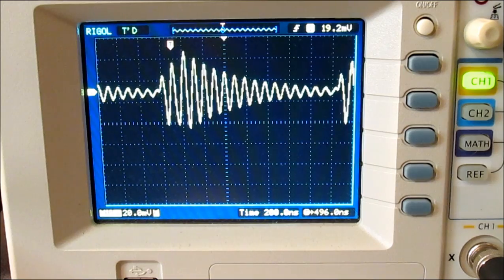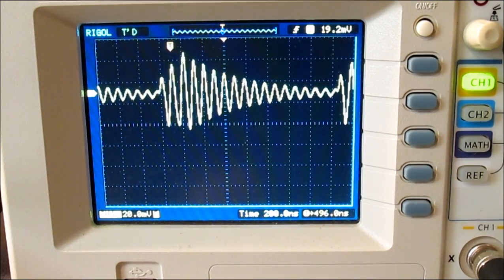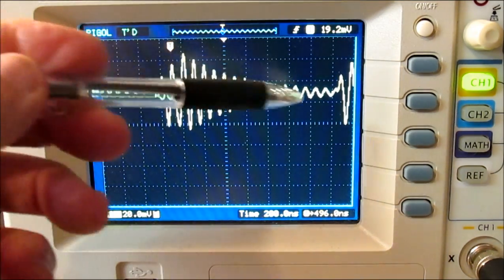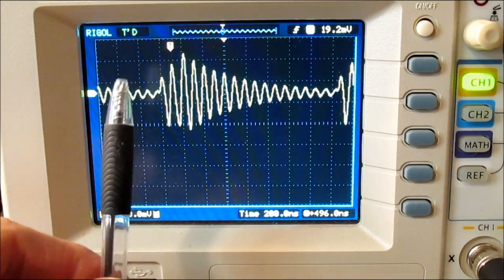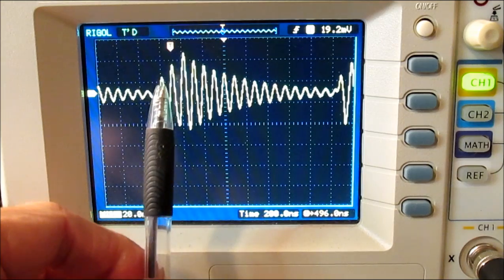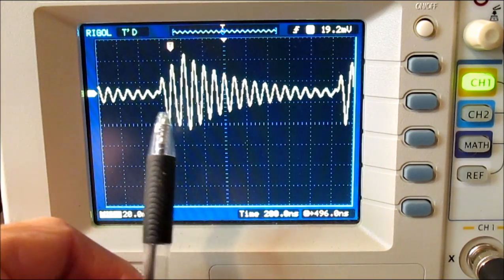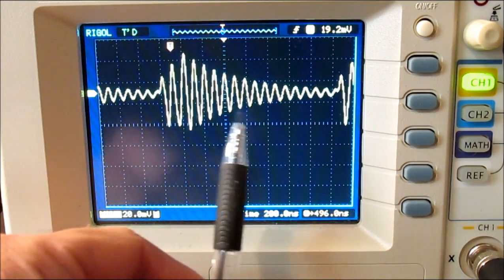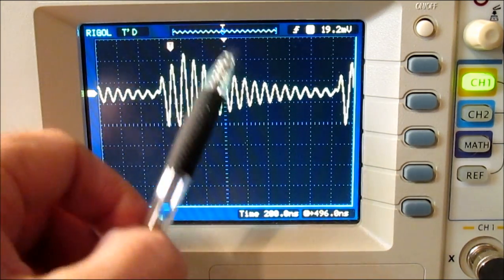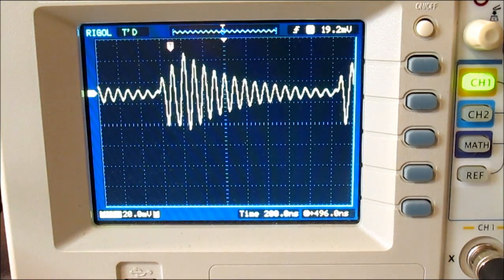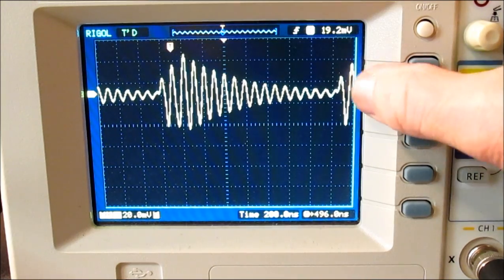Alright, now here's the oscilloscope with the ringing waveform on it. You can see when you're looking at the left edge of the screen, the amplitude is greater, and then it slowly goes down. It's getting hit with the pulse energy, causing it to oscillate, and then the pulse is removed because the duty cycle is such that it's on a short duration and off for a longer duration, so that oscillation is slowly dying out, and then it starts over on the next pulse over on this side.